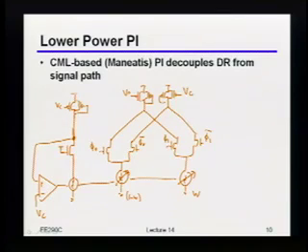No. Okay. So if I just looked at this circuit here, this op amp is just saying whatever VC is, that's what I want to put right here. So imagine that I made this 100 millivolts lower than the supply voltage. This op amp is going to tune this current source so that whatever that current is, when it goes through that resistance, it gives you a swing of 100 millivolts down from the supply, okay?